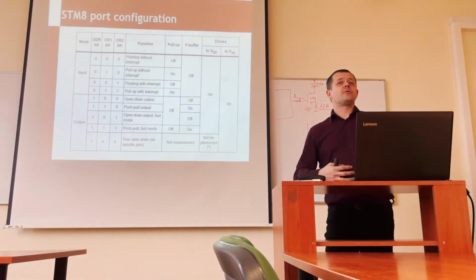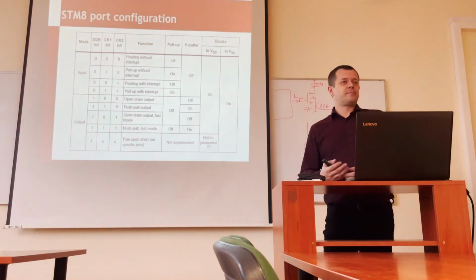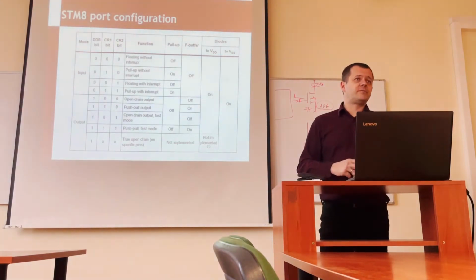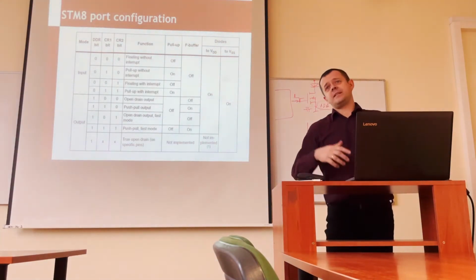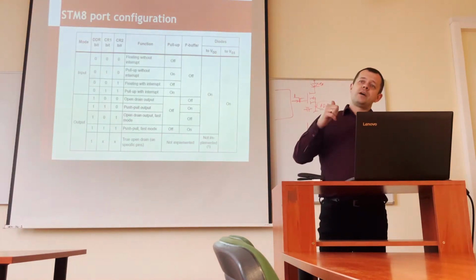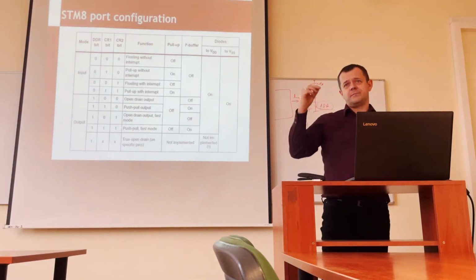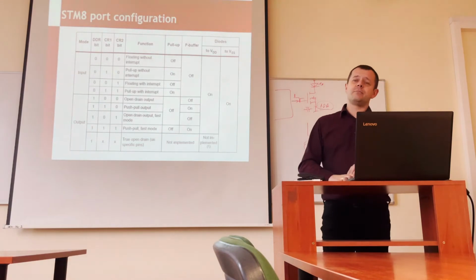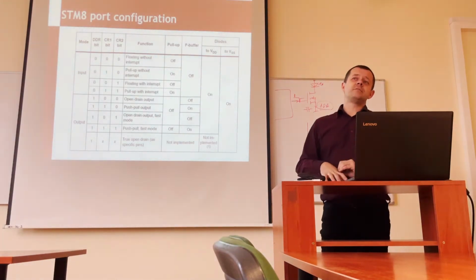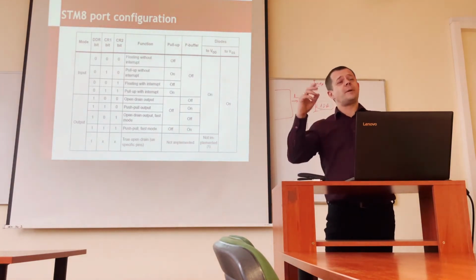But of course, it's completely impractical for each pin to have a dedicated interrupt vector. So we have some aggregation. There is a multiplexer that multiplexes the pins, and it depends on the microcontroller. Sometimes there is one port, one interrupt, so we have a multiplexer that multiplexes the pins to one interrupt. Sometimes we have a slightly different model, where each pin number is aggregated from any port.